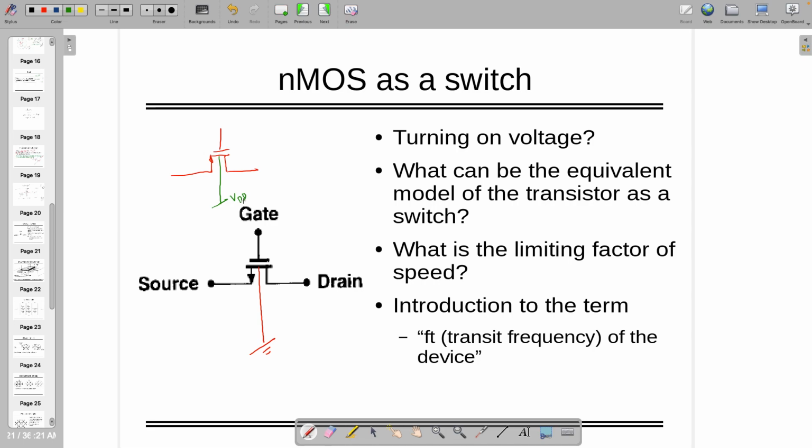From any side you can give input, sine wave, right? Look, there are 2 things: biasing, and the input. So I am talking about the sine wave input. The sine wave input can be going from anywhere. Even this ground is not completely ground. If you have seen it, there's 0 volt. If you look at the oscilloscope, you will see that it's not exactly 0 volt. It's moving here and there.